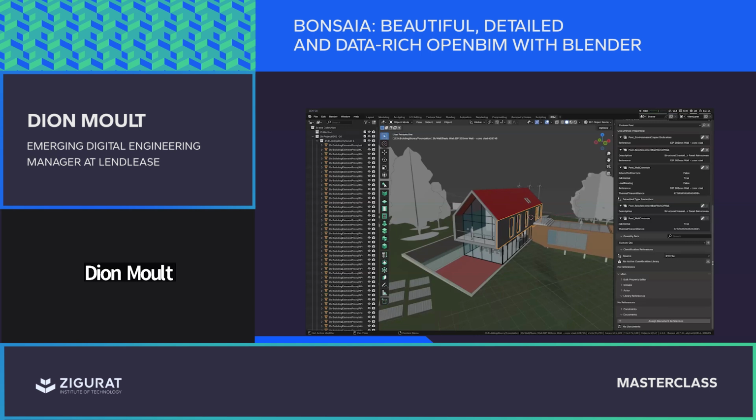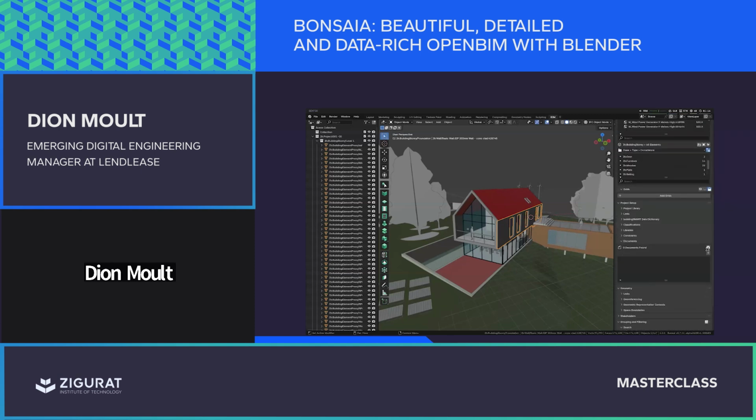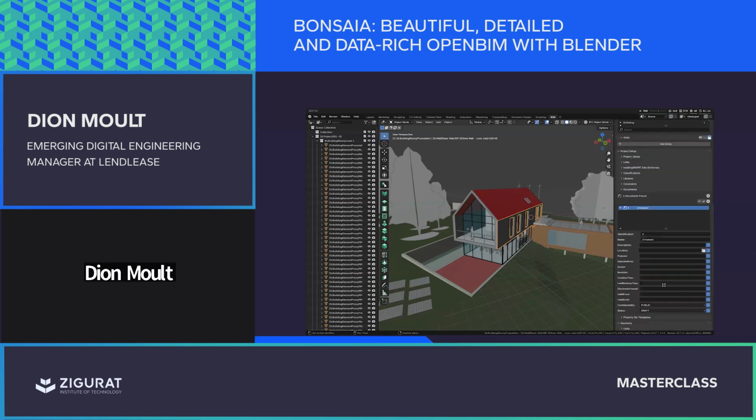And that is one of the really critical uses for operations and maintenance when you are maintaining a facility. Of course, since this model comes from Revit, Revit does not export that particular data or even understand anything about the facility world. But that's where tools like Bonsai come in. We can now, if we attach some documents to our project, start to enhance and edit this IFC. We can add a new document over here and start giving the revision of the document that all complies with ISO 19650 and so on.